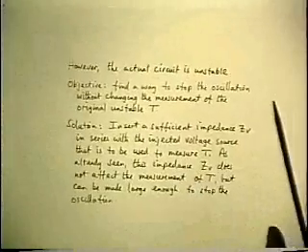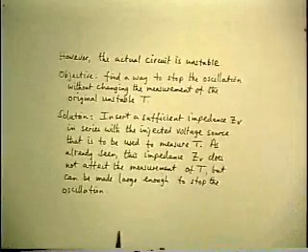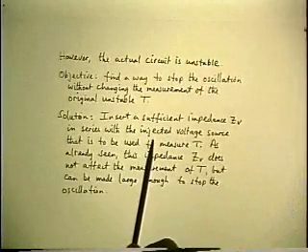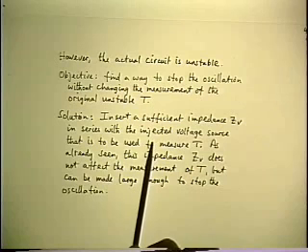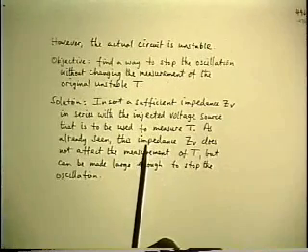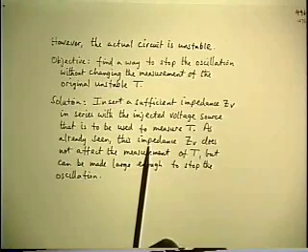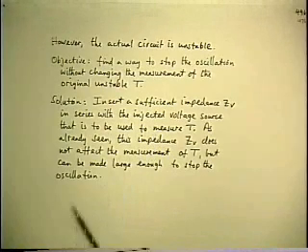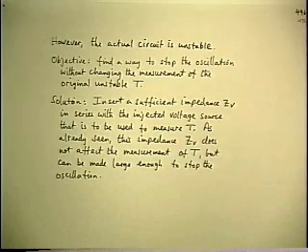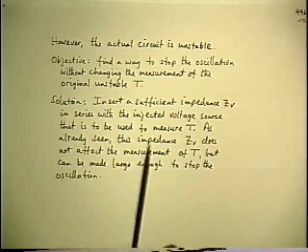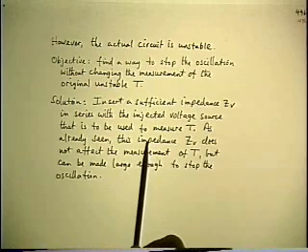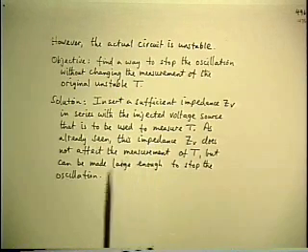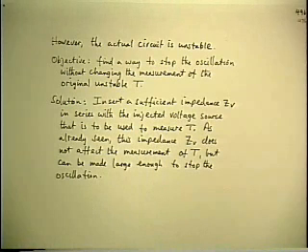What you do is, you do in fact have to change the loop in order to stabilize it and be able to make any measurement. And the key is, you change the loop and make it stable by changing it at one specific unique point, namely at the point where you're going to do the signal injection. In other words, you put that extra impedance in there.